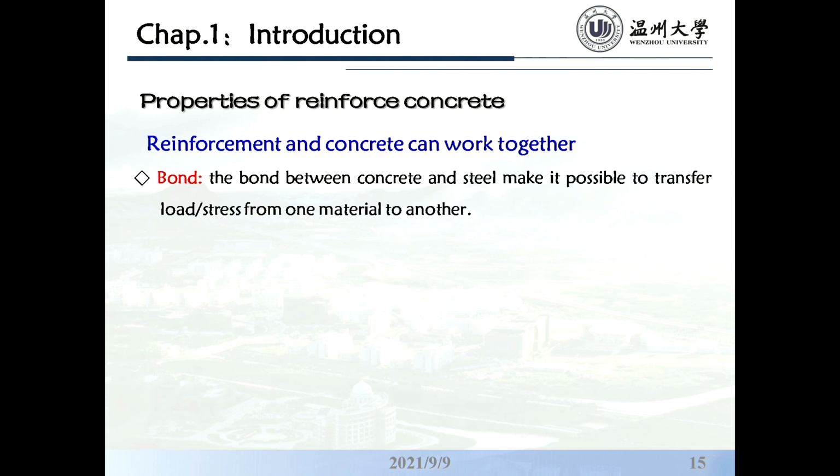This is a steel bar. Some steel bars, the surface is really smooth, but some steel bars have ribs. Using ribs is also true, because you can imagine, for the concrete, using ribs increases the touching surface with the concrete.